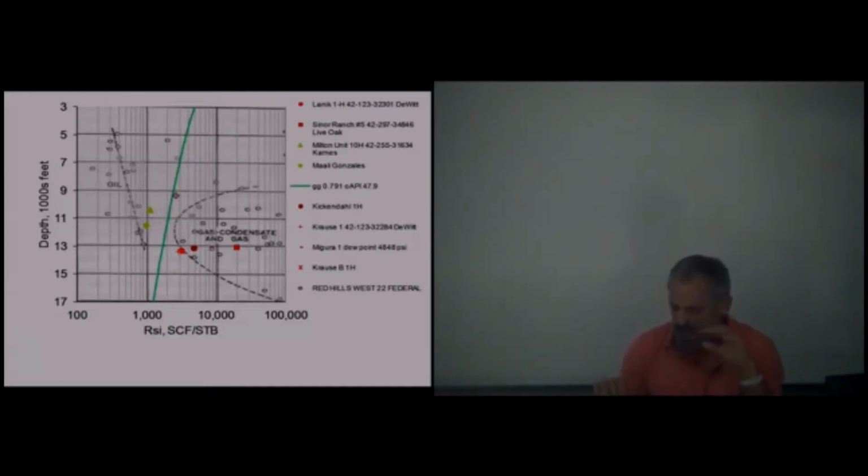The only way you know whether you're above or below the critical point is looking at it through the window, by bringing a complete subsurface sample to the surface, putting it at reservoir temperature and pressure, and then bringing it below the vapor liquid equilibrium line, the whole line where there's dew point or bubble point, and seeing whether a drop appears or a bubble. That's the only way you could know.